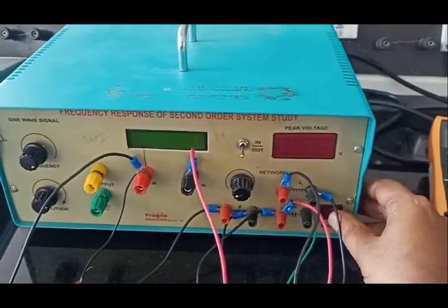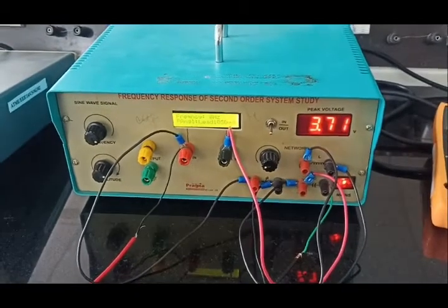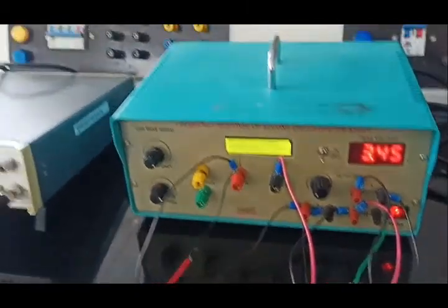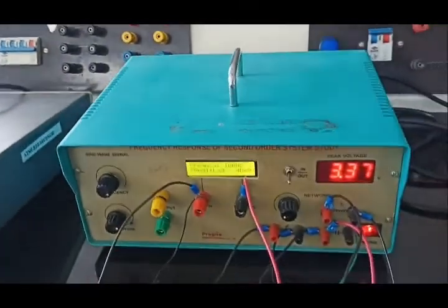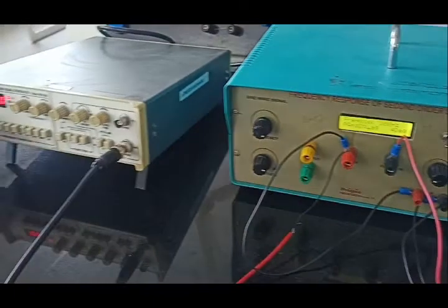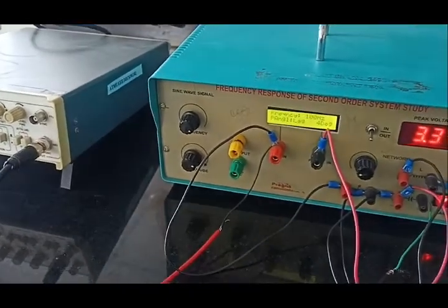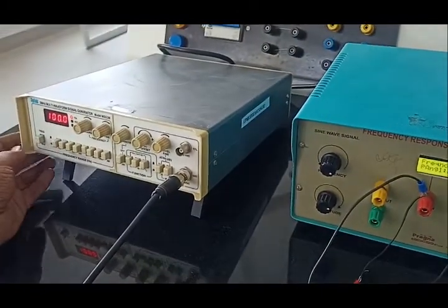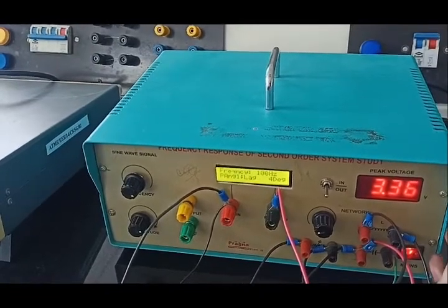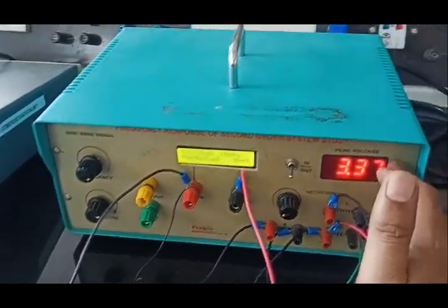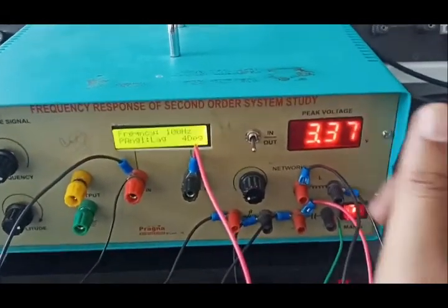Okay, so now let me turn on the module, and you can observe here the frequency I have set is 100 hertz. In the signal generator, which is the external signal generator I am using because of the kit constraint, which is of 2 kilohertz. This kit will measure the frequency as well as the phase angle, and this is the output voltage. Let me make it clear here, the peak voltage will be recorded, not peak to peak.